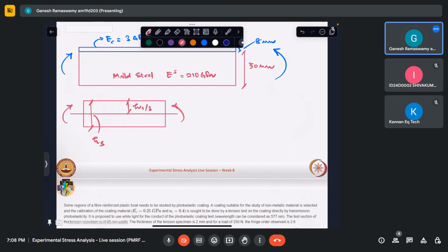Now we have coated this. So essentially, we have provided asymmetrical stiffness. Because of this bending, the response will pull the neutral axis above a little bit, because there is stiffness accumulation on one side. So the neutral axis gets pulled a bit. What they are asking is to find the position of the neutral axis measured from the top of the specimen. If it was at 15 by 2, it got pulled a little, so what is the new position is what is being asked.